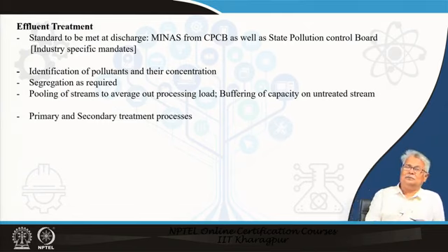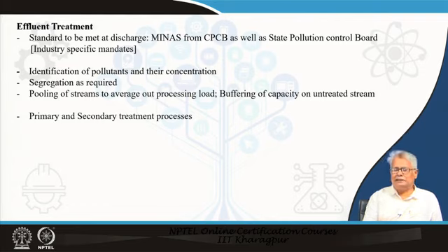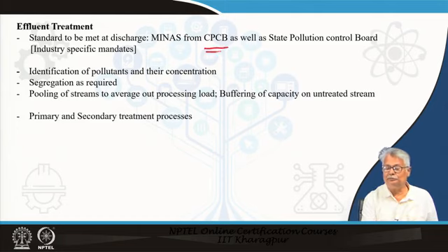At the end, before I conclude, I have spoken about the utilities in very brief, but your plant design is never complete until you have handled all your effluents. Any process will generate effluent. Right now, I am talking about the liquid effluent, which is mostly aqueous. It is essential for you to know that before you discharge any liquid effluent or even a gas effluent, you must meet the norms, and these norms are set by the Central Pollution Control Board as well as the State Pollution Control Board.